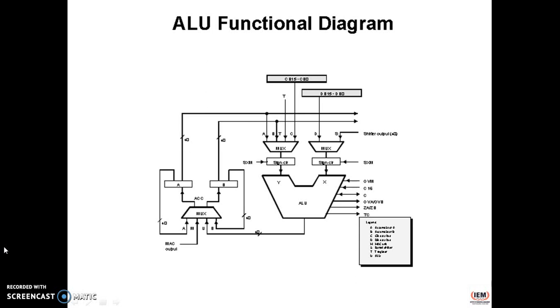The multiplier adder block consists of several elements: a multiplier and adder, sign unsigned input control logic, functional control logic, zero detector, a rounder, 2's complement overflow saturation logic, and a 16-bit temporary store register.